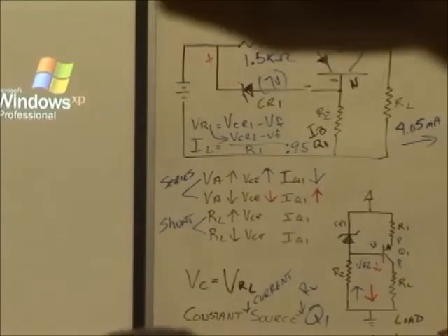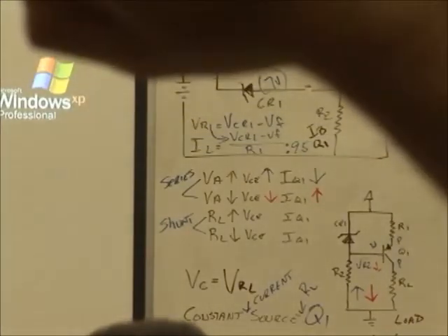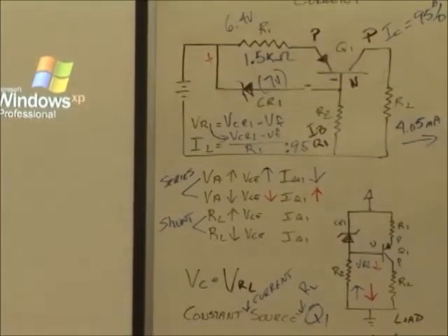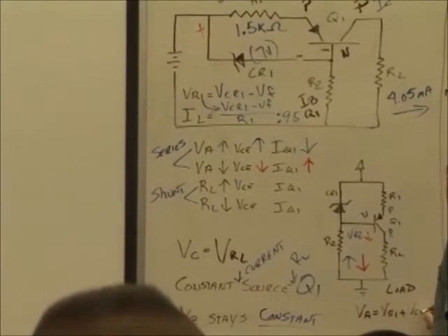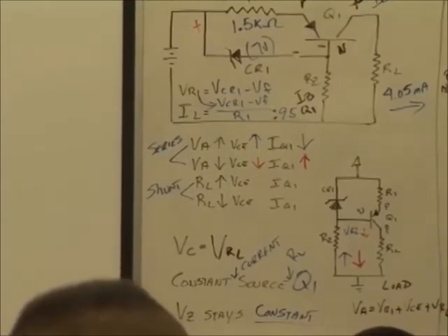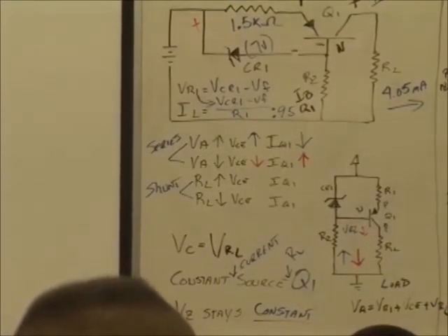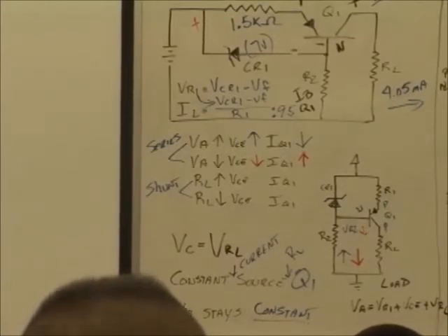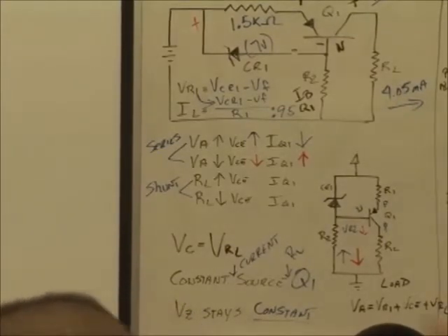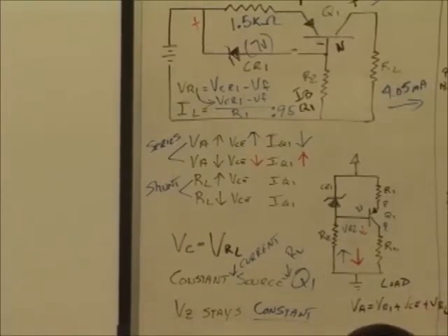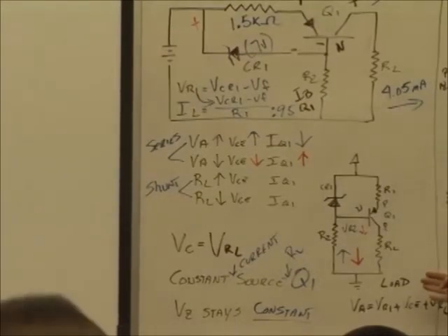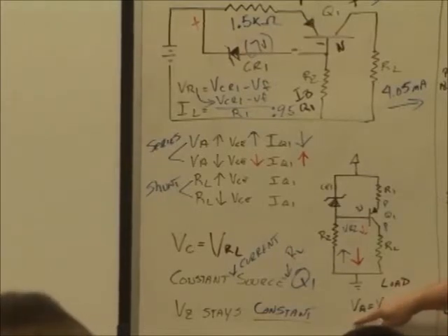What's the formula that I gave you for this? Somebody's got it. What is it? VR1 plus VCE plus VRL. That's what I told you to do for this side. I'm giving you the answers. I'm giving you the help. It's all here. I'm explaining how it works. This is just Kirchhoff stuff. For the load side, do this. Because the line voltage isn't going to change this time, is it? No, it's going to stay the same.